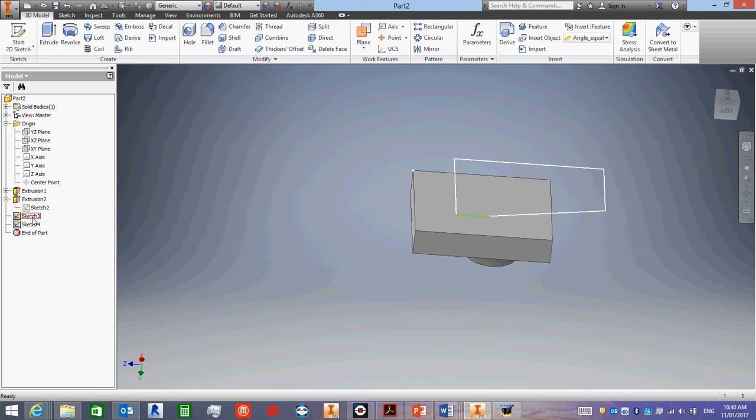If I hold the mouse over there, you can see the sketch changes, and you can see which sketch does what. Now Inventor, when it does an extrusion, only looks at one sketch at a time. It doesn't glue these two sketches together. So even though this shape looks solid, looks like it can make a solid shape, Inventor only ever sees that, or it only ever sees that. So it can't make a solid shape out of them.